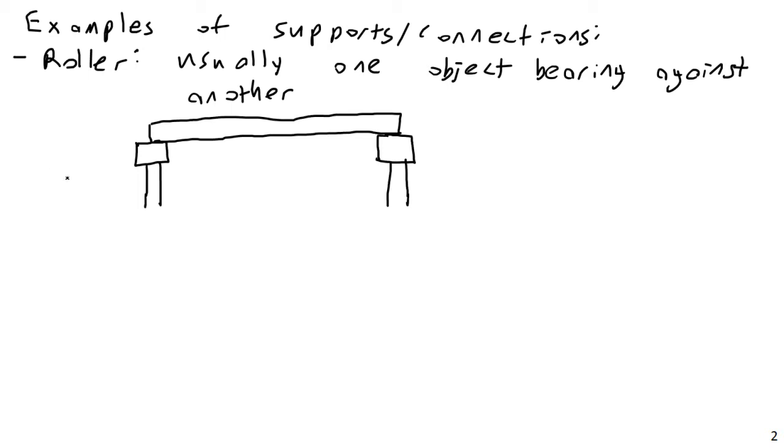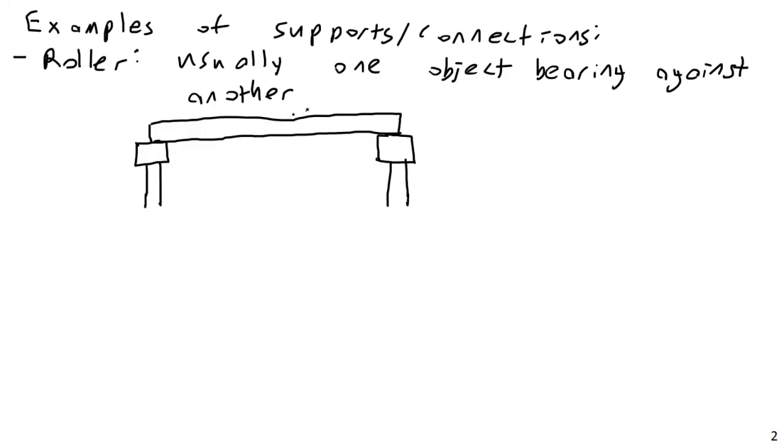However, when we talk about pin and roller supports, we're always talking about something in proportion. So yes, lateral frictional force does exist in here, but compared to the actual strength of the member, like the force that would be required to fail this girder in tension, that frictional capacity of that joint is going to be minuscule compared to the tensile capacity of the beam. The beam's going to have 10 or 50 times that.